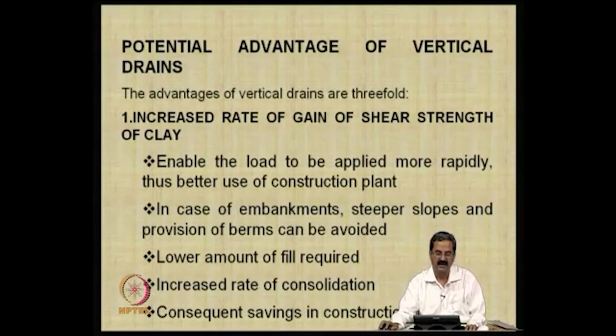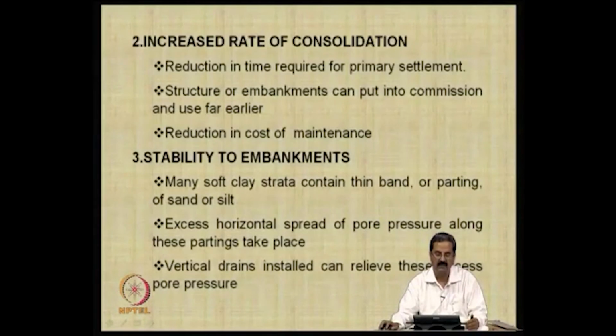So, the advantages are that it leads to increased shear strength of the clay, and it enables the load to be applied more rapidly, thus better use of the construction plant. In the case of embankments and steeper slopes, provision of berms could be avoided. Sometimes provision of berms to improve stability is one of the standard techniques normally done. Lower amount of fill is required, as I just mentioned. It greatly helps in reducing the amount of preload required, and it saves a lot in the construction.